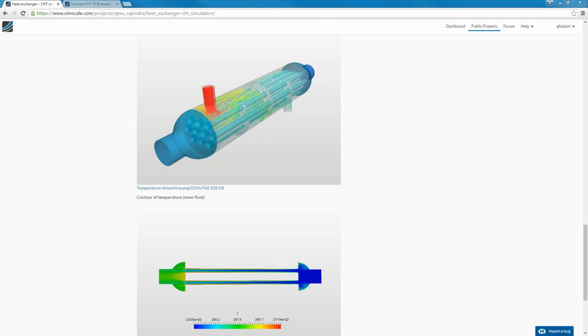If you go through the kind of boundary conditions we have for temperature, you will find a few other boundary conditions that are more complex and give you more possibilities to assign as an external BC. Okay, we also have a question. Would it be possible to simulate the solid with a thermal output instead of a given temperature? Of course. So what you can do, this also is covered under those boundary conditions. You can create a boundary condition that generates heat at a certain rate. This is how you do it.